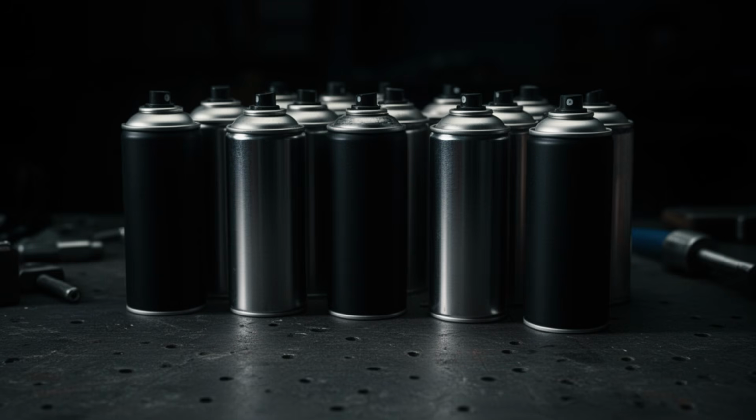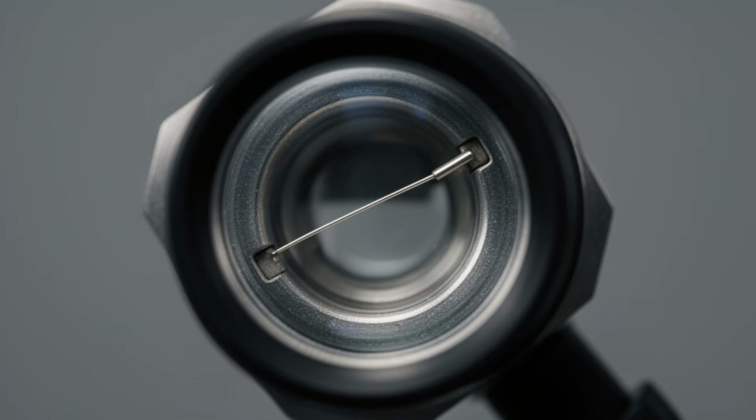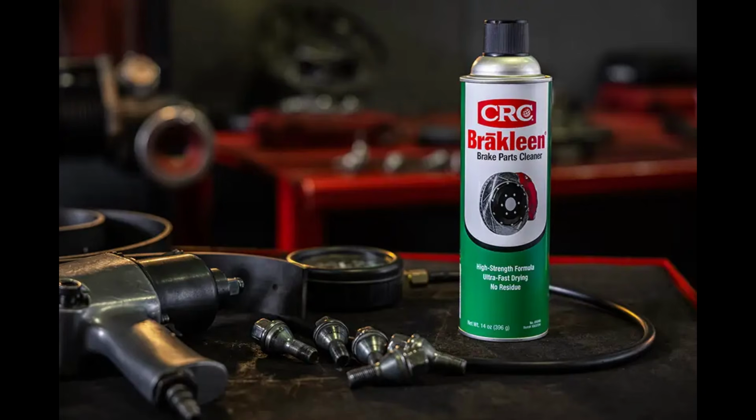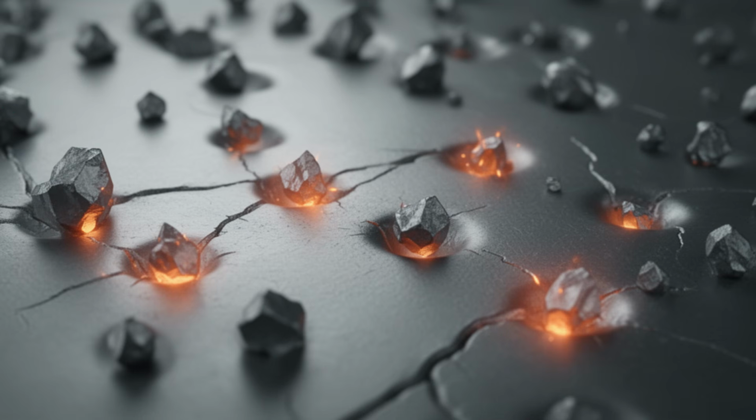Brake cleaner, carburetor cleaner, general-purpose electronics contact cleaner, WD-40, compressed air, none of these are acceptable. The sensing element is an extremely fine platinum film on a fragile ceramic substrate. The electrical connections at the base of the element are microscopically thin. Brake and carb cleaners contain chlorinated solvents that will chemically attack the platinum coating. Compressed air alone will drive particulate deeper into the sensor housing without removing it.